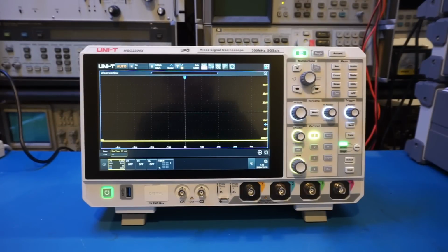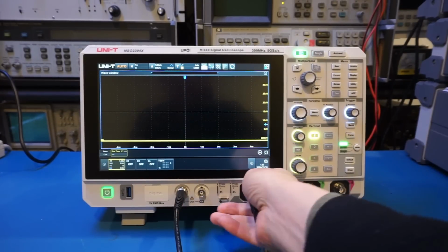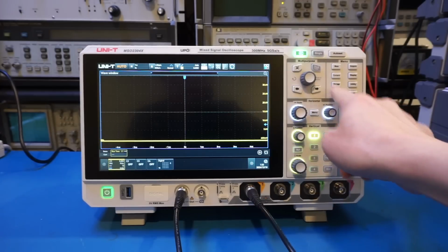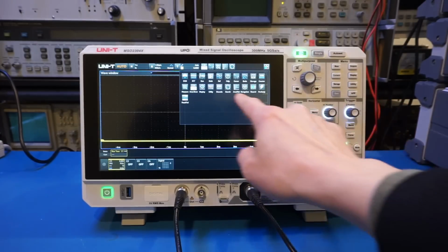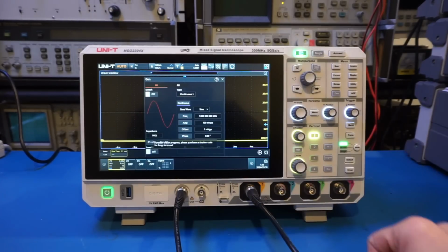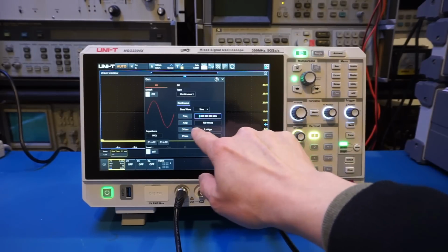Now let's take a look at the frequency modulated signal with the scope. With the MSO2304X, it's actually kind of convenient as we have the built-in function generator. So let's use the function generator to generate that FM signal here. Let's bring up the function generator. By the way, you can bring it up here, or you can use the menu here. Let's just see. We have the generator, and let's generate a sinusoidal frequency. Let's do 1 megahertz.